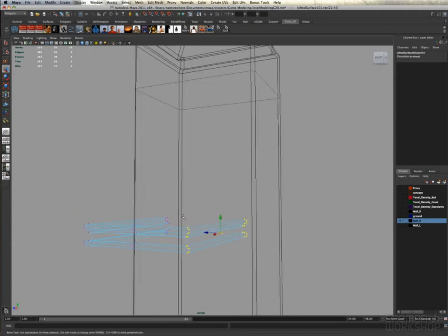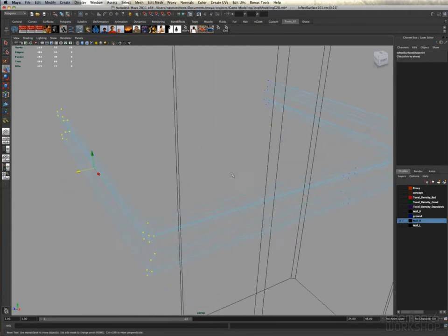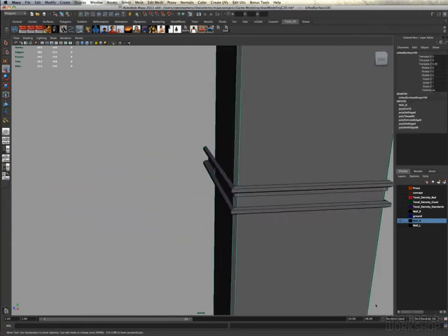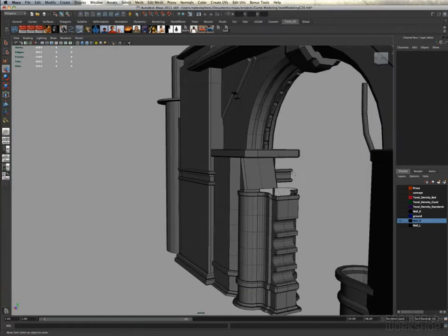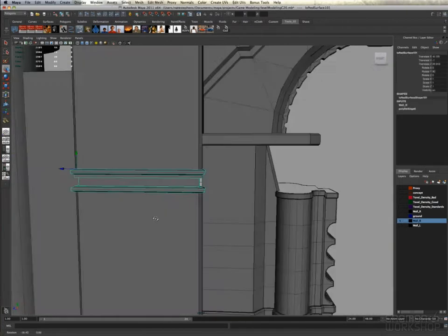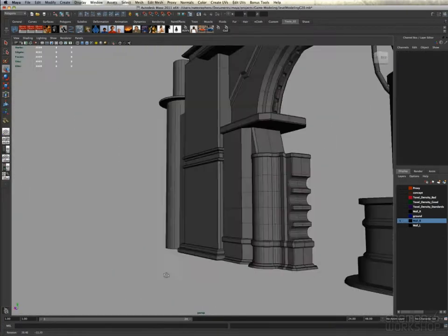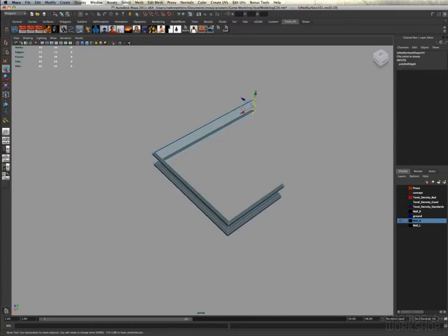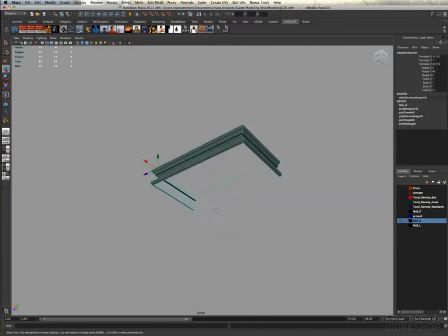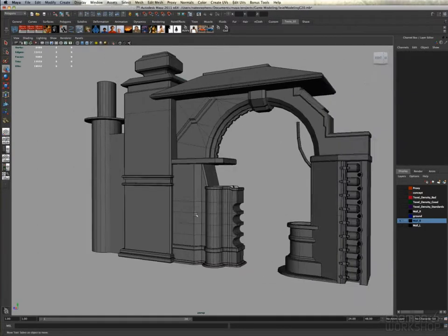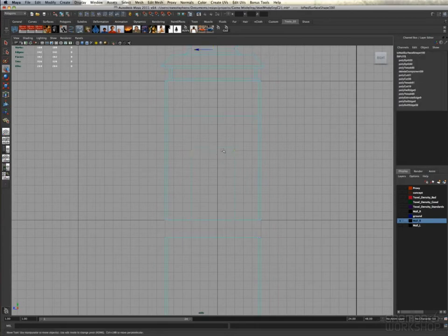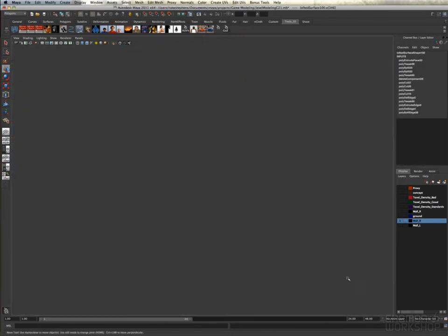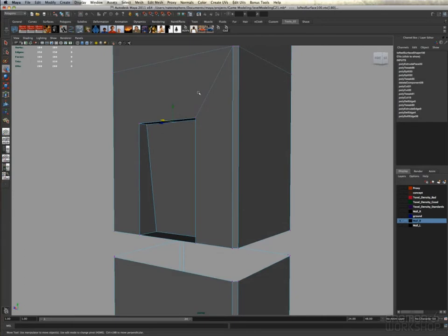And what I'm doing right here is stealing another trim from the other side, and I'm going to repurpose this for the center area of this sci-fi pillar, smokestack, whatever it is. And like I said a couple times already, this is a very efficient way to work, because eventually when I do my texturing, I don't have to texture a million different pieces. In a scene like this, I'll only have maybe 6 or 7 different trim pieces, and I just reuse them all over, saving memory, time, and texture space.